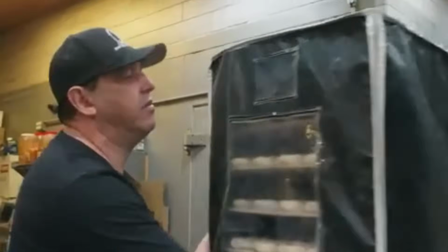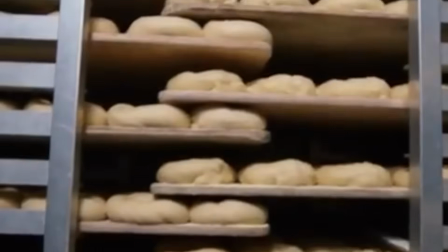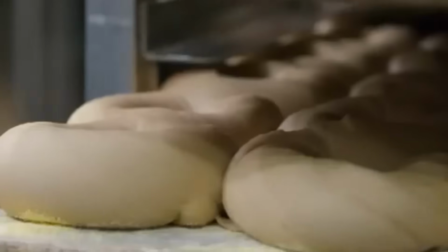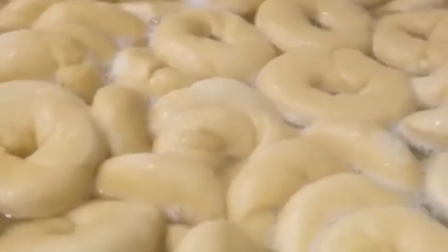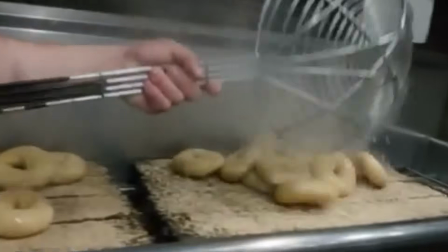Formed bagels are deposited onto a wide, dusted conveyor belt, each one spaced perfectly from the next by indexing arms that keep rows uniform as they head toward the proofing section. At this stage, the dough is still dense and compact and needs controlled time to relax and ferment before any further processing. The trays of raw bagels enter an enclosed, temperature and humidity regulated proofer where warm, moist air surrounds the dough, gently encouraging expansion without aggressive rise.